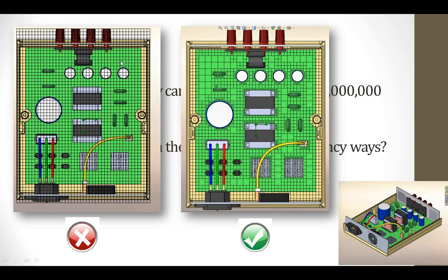On the left side, the meshing is very even, with no big or small sizes, all the same size. However, on the right side, not all are the same size. Around here the size is bigger, and near the electronic components, the size of the cube becomes smaller and smaller. Why is this a very good meshing? Because around here there are no electronic components. Why do we need to focus on calculating here?